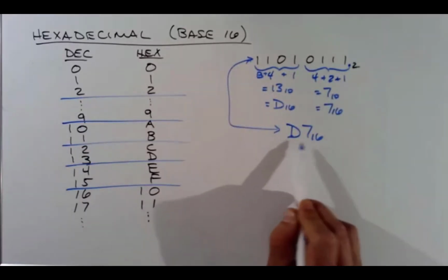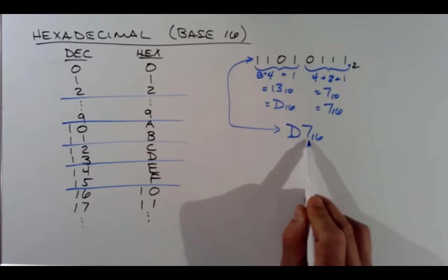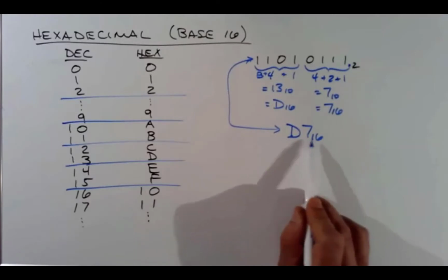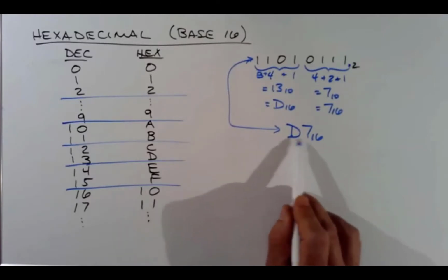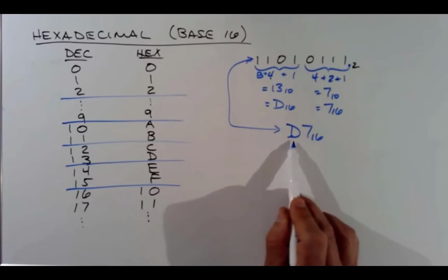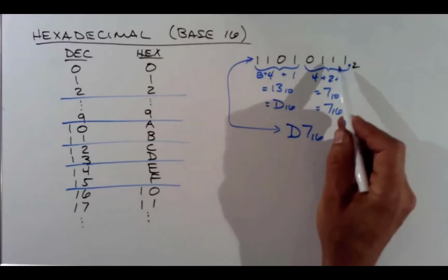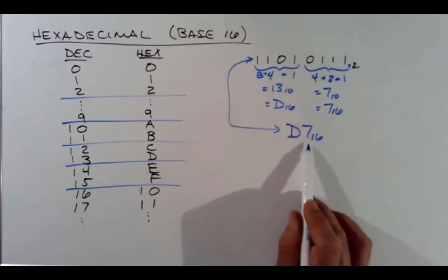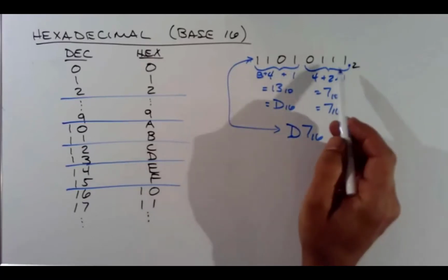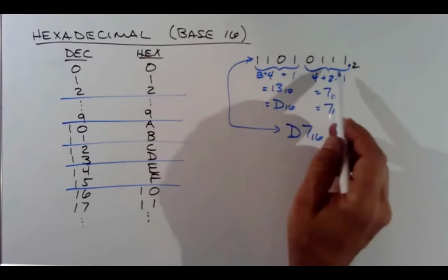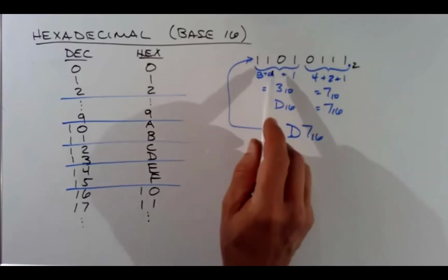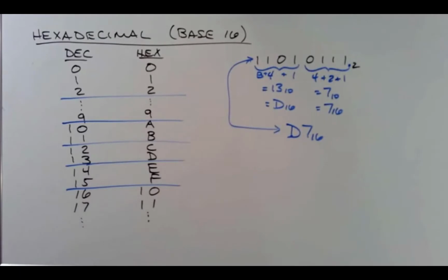And I can just concatenate those because remember, each digit is like multiplying by the base. So if I shift a digit in binary, it's like multiplying by 2, right? If I shift a digit in hex, it's like multiplying by 16. If I shift 4 digits, right, 1 nibble over, it's like multiplying by 16, which is what I've done here. Okay.